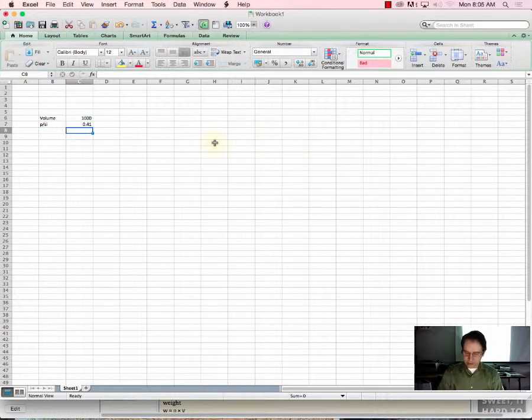So we'll say pounds per cubic inch. And then the total weight of the object would be the volume. So this is the number of cubic inches I have times the weight per cubic inch. So a 10 inch by 10 inch by 10 inch cube made of lead would weigh 410 pounds. That's crazy heavy for a pretty small cube object.